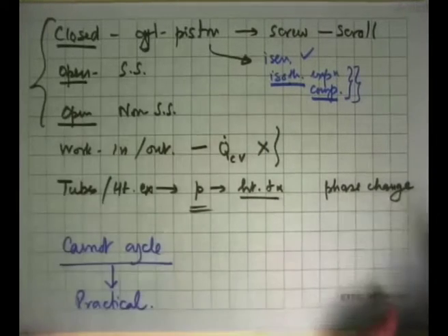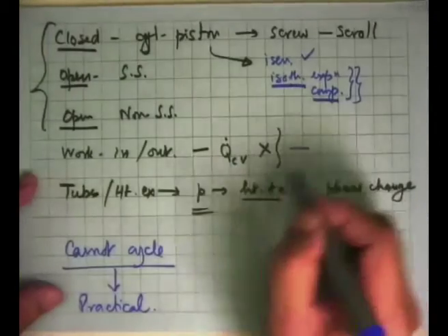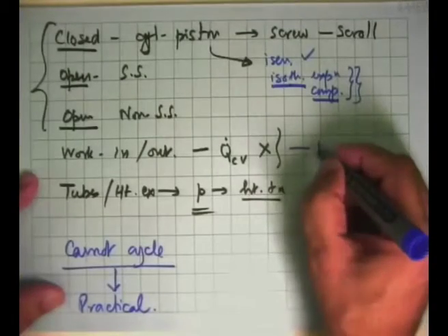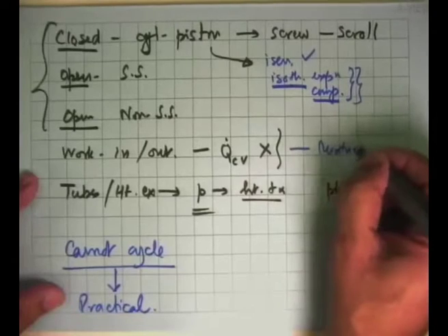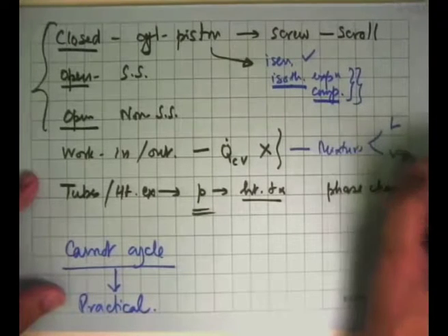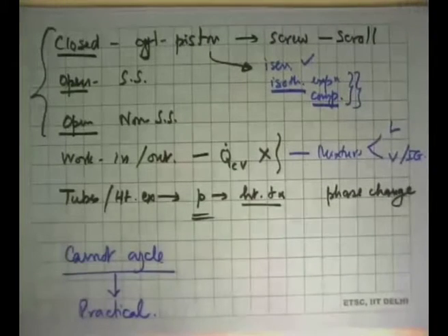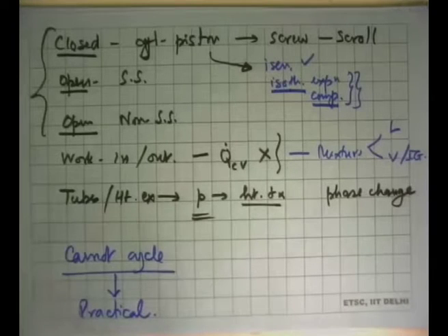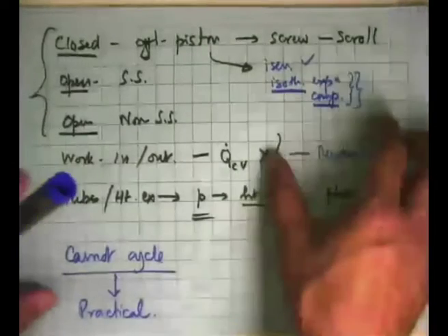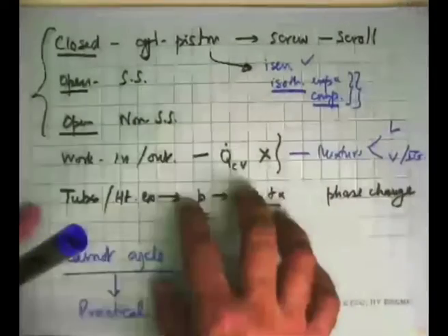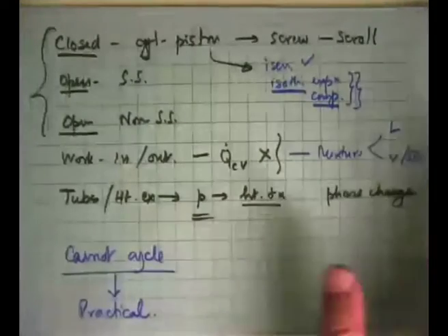The other thing we looked at, we cannot make a work producing or a work consuming device which has a mixture. It has to be either fully liquid or it has to be fully vapor or an ideal gas. We cannot pump in a wet state. We cannot expand wet steam very much in a turbine. Up to 0.9 quality we can do it, 0.6 quality, 0.3 quality is not possible. So thermodynamics tells us you can do it, practical engineering tells us not possible, don't worry about it.